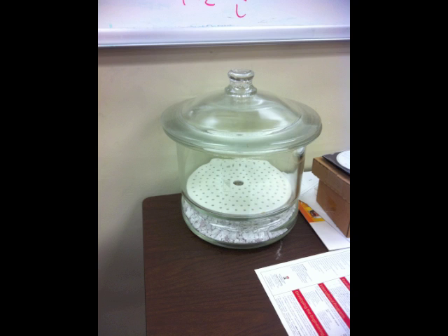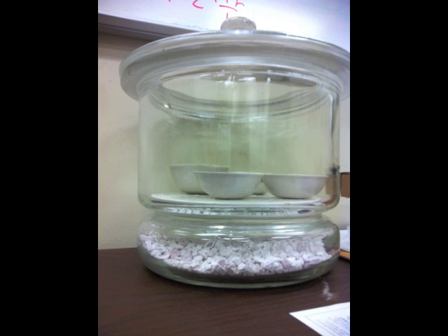The total solids were determined as 310 milligrams per liter and made up almost entirely out of dissolved solids. This means that the suspended solids will not need to be pre-filtered to prevent pump failure or column clogging.